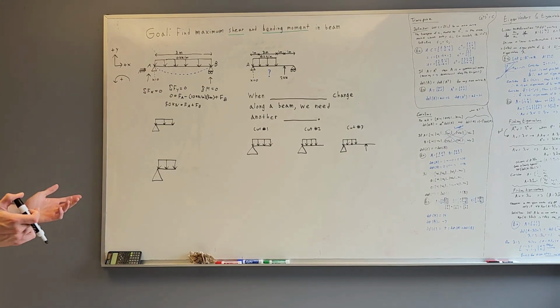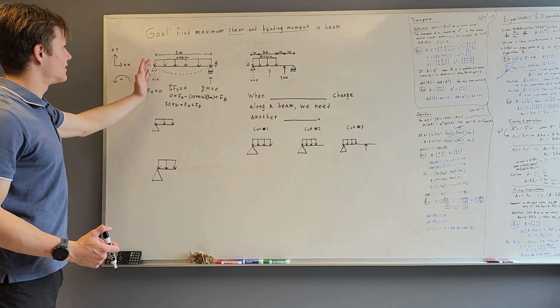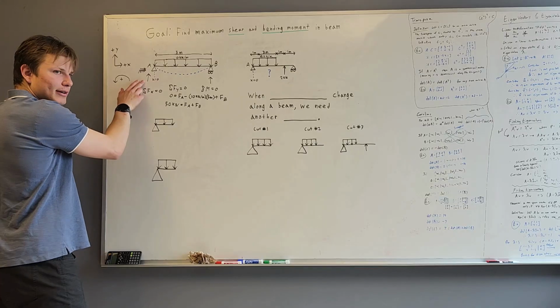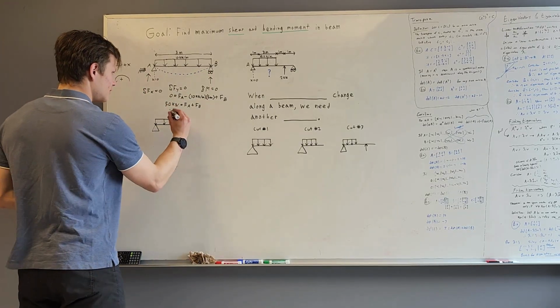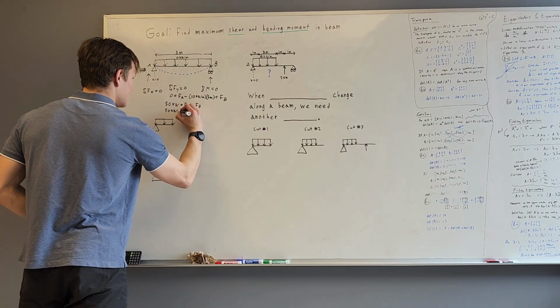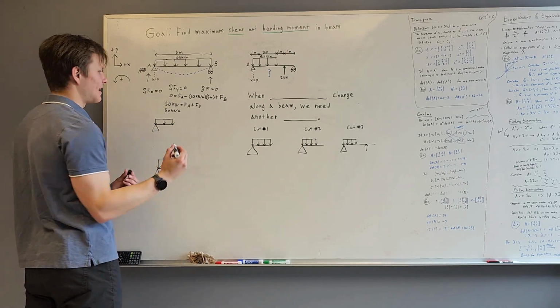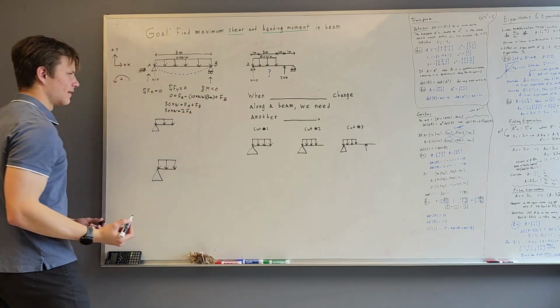However, we can just keep it simple for now because we know that this beam is symmetrical. And so the force at A is going to be equal to the force at B. So really, we know that 50 kilonewtons is equal to, instead of FA plus FB, that's the same thing as having 2 FA.